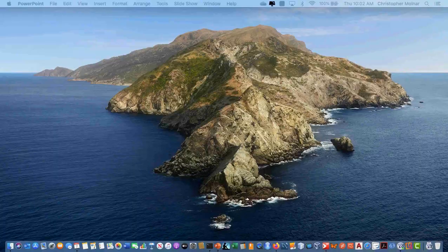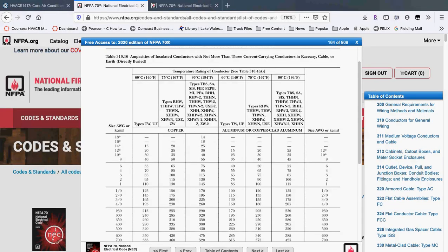Yeah, I have a question about the capacitor. About the capacitor? Yeah. What's the question? I want to know, as in residential, what kind of capacitor is used, like a run capacitor or the start capacitor? We use both. Run capacitor is always in the circuit. Start capacitor comes out of the circuit once the motor reaches 75% of its speed.